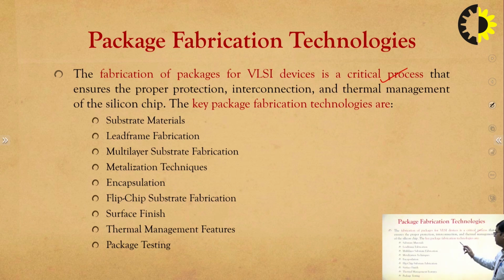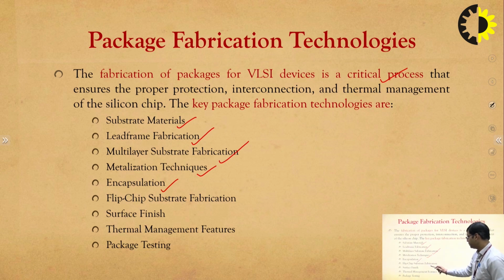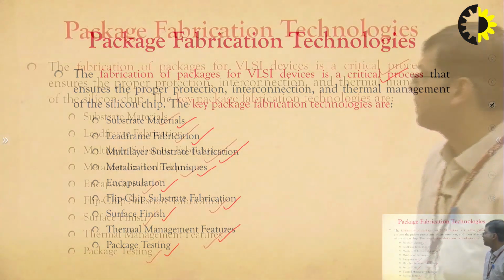The key package fabrication technologies are the substrate materials, lead frame fabrication, multi-layer substrate fabrication, metallization techniques, encapsulation, flip chip substrate fabrication, surface finish, thermal management features and package testing.